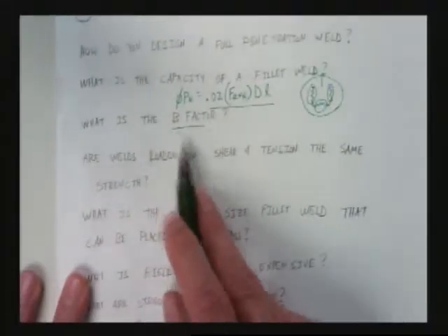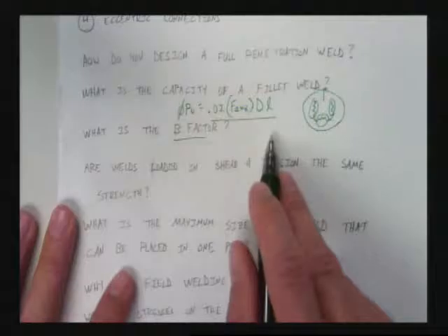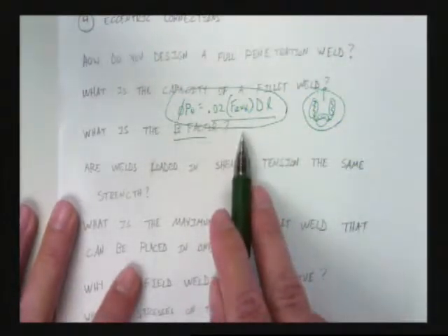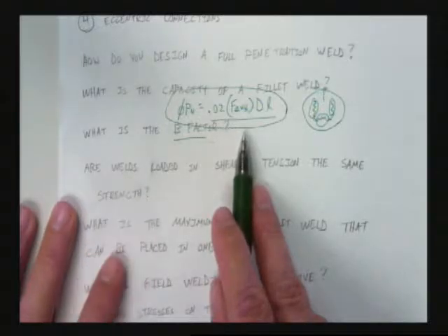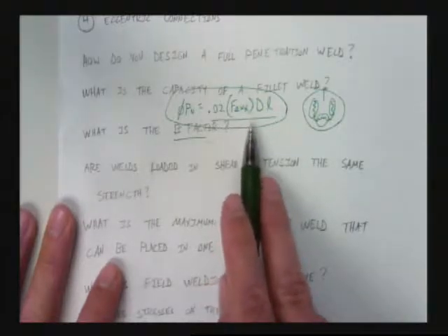That's a modifier? What's that? That's a modifier? You multiply it by... Yes, sir. That 1 plus sine theta is a modifier to this equation. It's a modifier to that equation. If you notice how that equation is defined when theta is 0, then that modifier becomes 1, and it's loaded in pure shear, and it's just this equation.